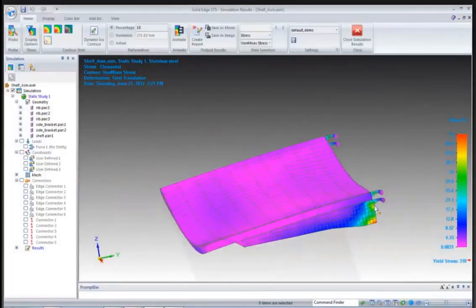the edges here, because in true life, really, I could not constrain an edge perfectly at that exact point in the y direction. I could not do that in real life. So I'm making an assumption there. And because stress is equal to the force over the area, when I make the area extremely small by making it an edge or a point, the stress gets infinitesimally high. It gets extremely high, and we call that a singularity. And we know, because you can see it here, there's high stress around where I applied those constraints. And we know that this is not our area of concern, so we're not going to look at that.